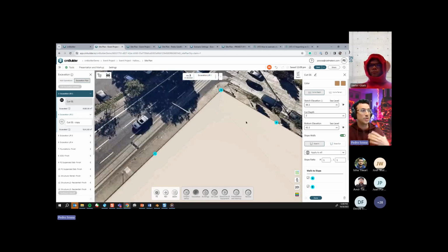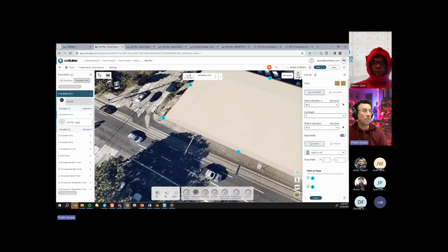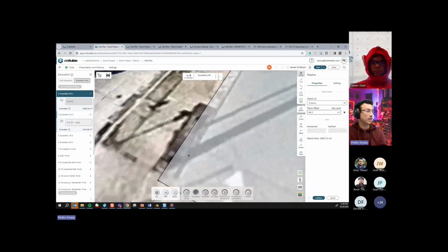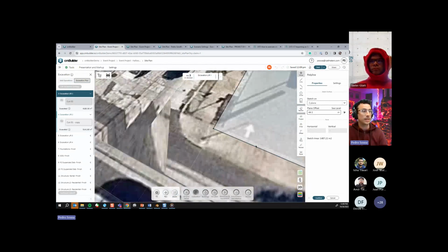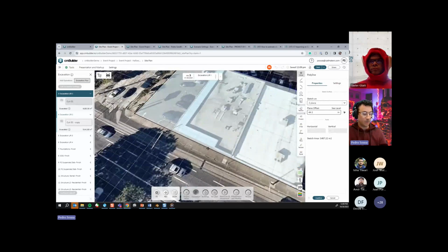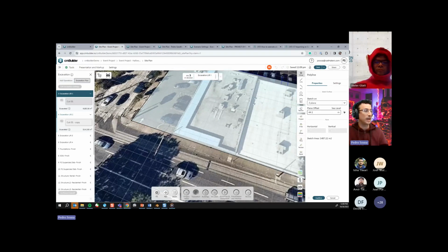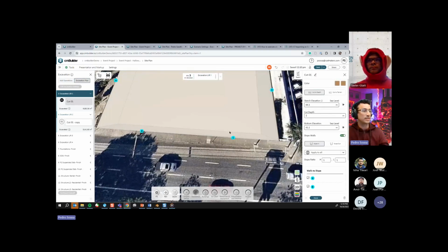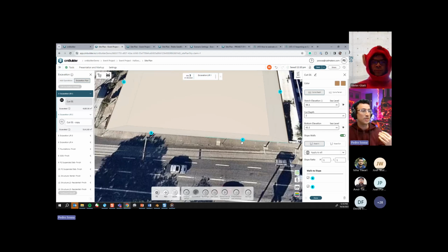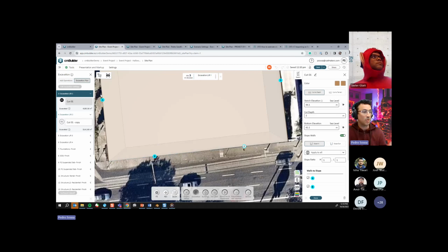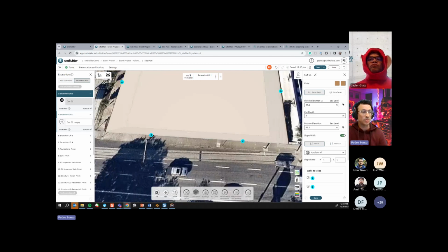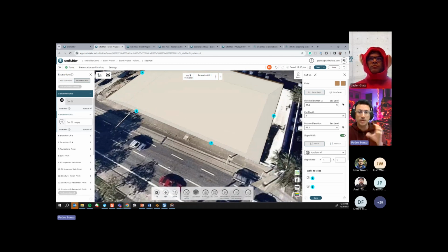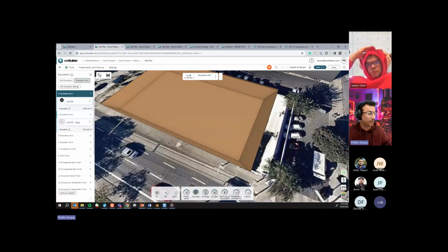To avoid that, you can simply go over here in your edit sketch, look for the location where you have those points, and then delete them, okay? Also, we suggest not having coplanar, collinear points like this one, so that you avoid having that same wall divided in two. Otherwise you have to work with both walls to remove the sloping and so on and so forth. Okay, just some quick ways for you to have a cleaner sketch to work with.